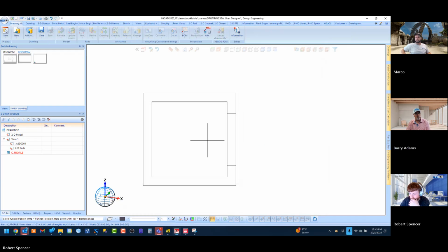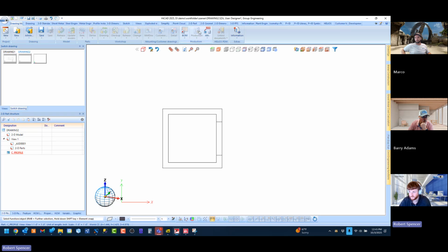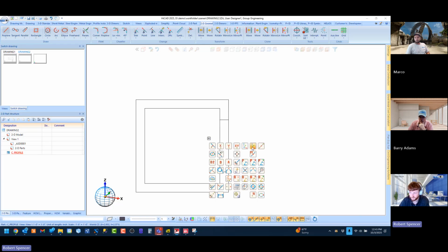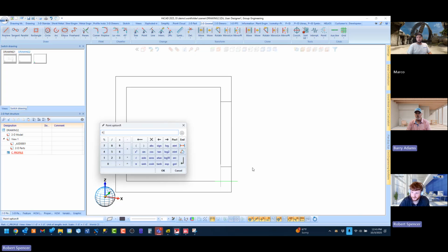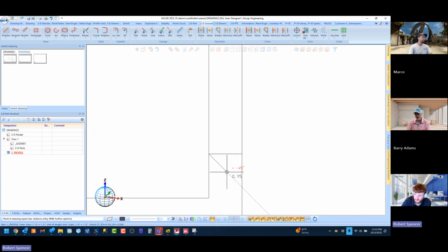Okay, so how did you get your from on that? So I've got line selected, and your from, you just click the from. Line, enter, from point. This line. I'm not sure whether you're working at the top or the bottom right now. Bottom. Bottom, and then reference point. And now you want it to be 0 in the X, 1/4 inch up in the Y. And now it's going to snap that to that point.